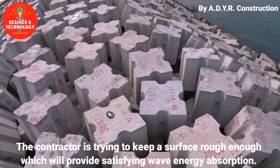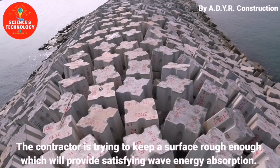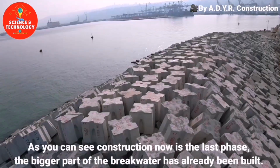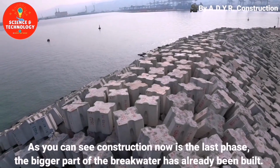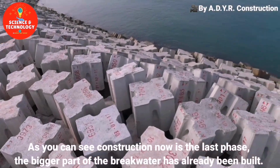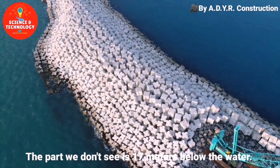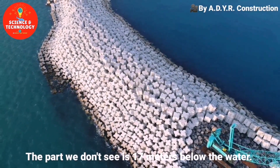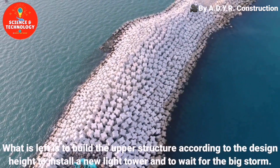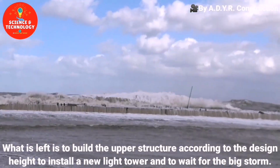The contractor is trying to keep a surface rough enough which will provide satisfying wave energy absorption. As you can see, construction now is in the last phase. The bigger part of the breakwater has already been built. The part we don't see is 17 meters below the water. What is left is to build the upper structure according to the design height, to install a new light tower and to wait for the big storm.